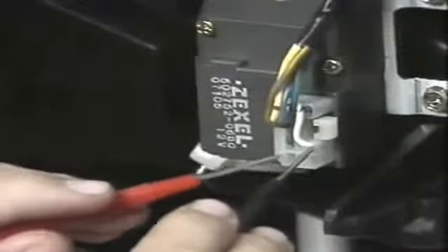The service manual also contains troubleshooting flowcharts for each fault code and for failures which do not have a fault code. Some troubleshooting procedures require testing with electrical connections made, while other tests will require readings with the components disconnected. Service manual flowcharts approach each failure in a similar manner. Each chart begins with the examination of the input and output device. Following this test, the chart leads to the ECU test procedures.